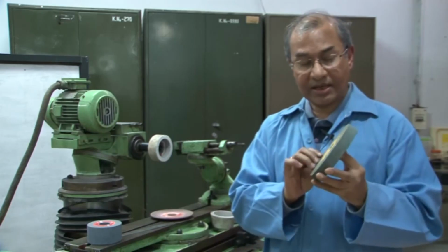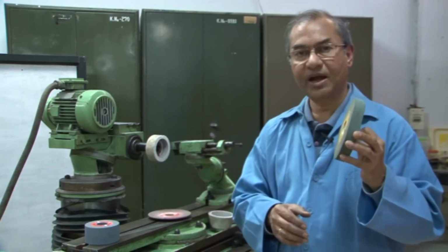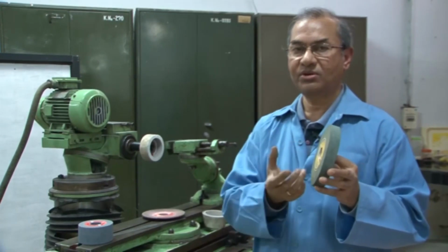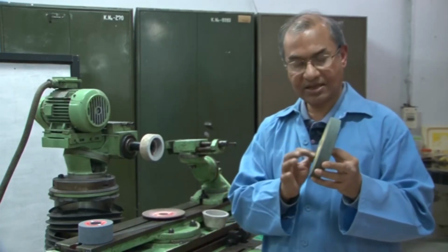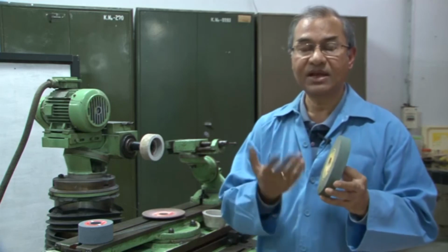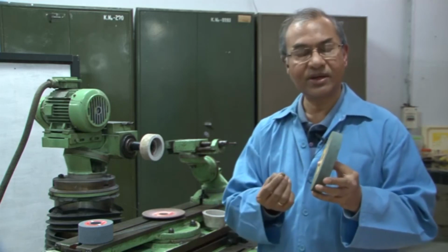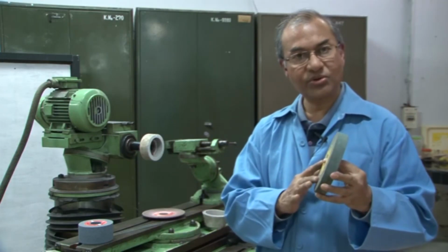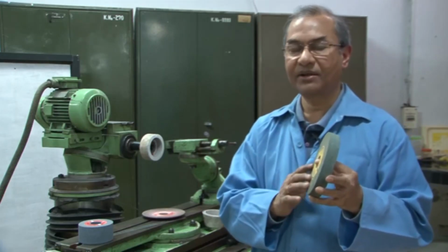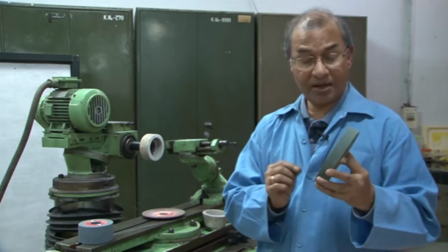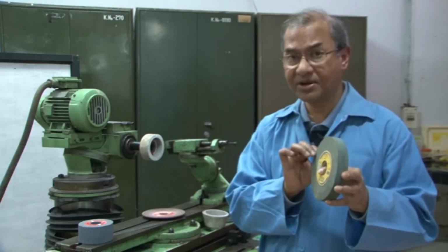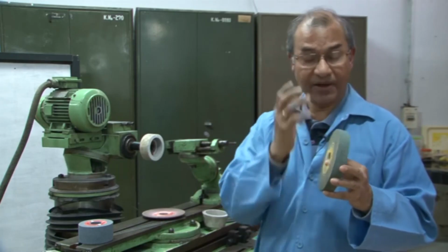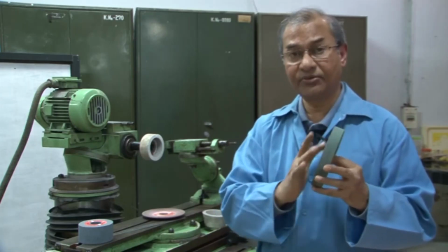The second parameter on which the performance of a grinding wheel depends is the size of the grain. Either you use a coarse size, that is the bigger size grains, or the medium size grain, or fine grains and very fine grains. So, these are the 4 basic grades available: coarse, medium, fine and very fine grains. Now, the diameter of the grinding wheel grains depends on the sieve number. So, the sieve number defines the size of the grinding wheel grain.